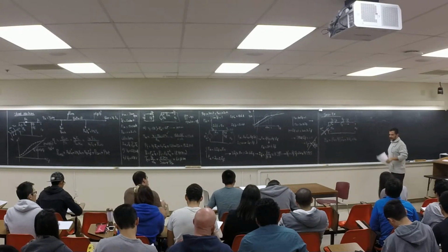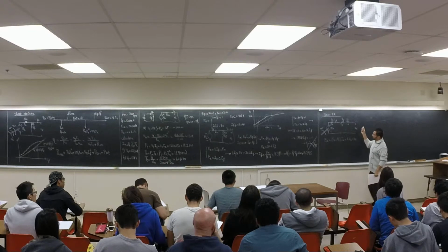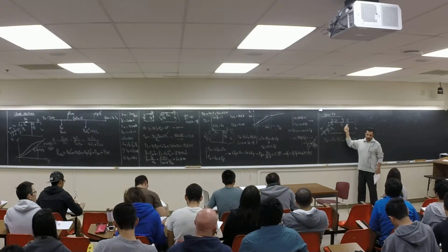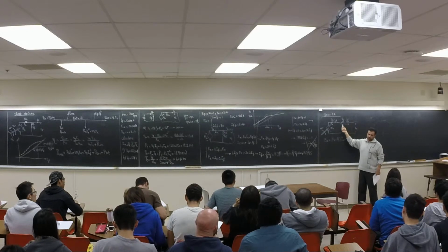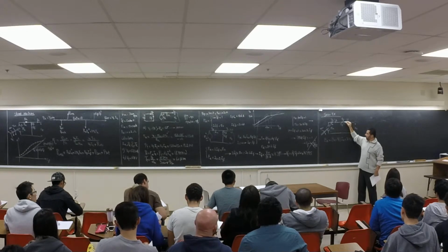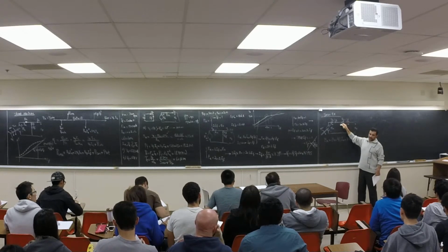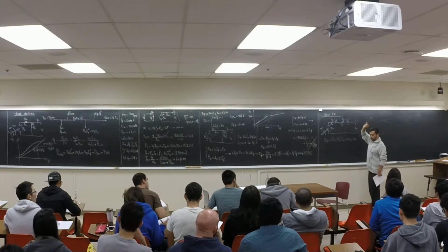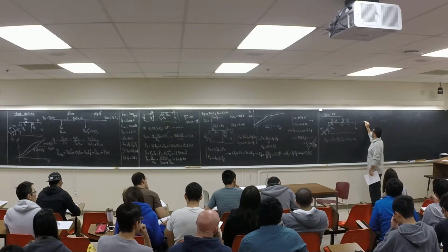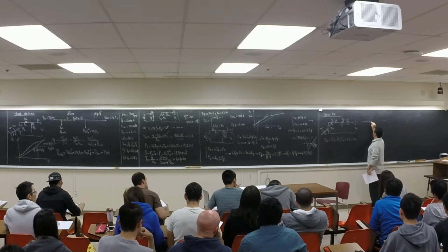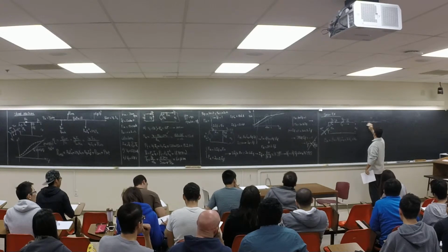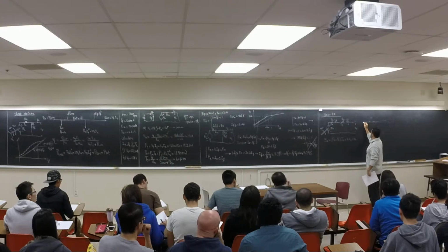But in reality, because you know for the control, you have to change the field, right? One way to control the machine was to change the field. Here we cannot change this one, because this is in series. You cannot make it very hard. What they do for control purposes is like this. They have this RA LA, and they have this RF LF. Let's just forget the L. Make it simple.